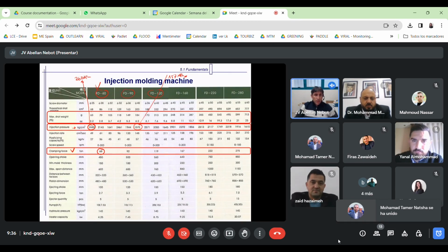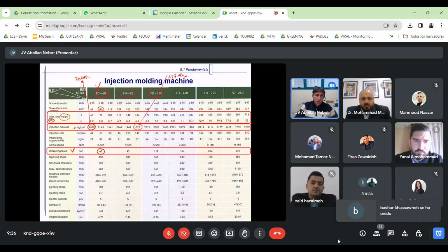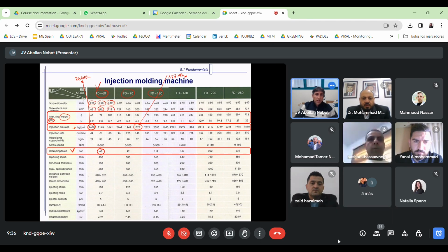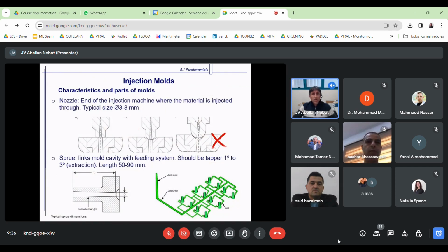And the volume is here, or the weight. You can see the weight with polyester, or the volume that we can inject. We can inject a maximum, for instance here in this equipment, depending on the screw diameter, depending on the type of screw that we have, all these different volumes. Okay, so this is just to show that it's important to realize that there are some conditions and requirements in the injection machines that we need to consider during simulation.